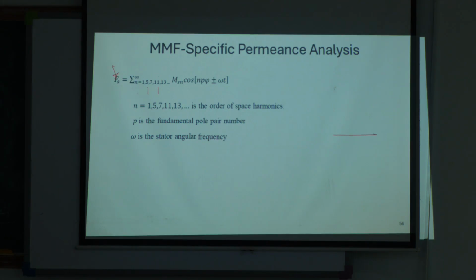If I take a 3-phase system, this is phase A, this is phase B, and this is phase C. If I consider this as positive sequence, if I multiply by 5, let's say this is a magnitude and an angle 0, this will be same magnitude but angle minus 120, this will be same magnitude, angle plus 120, right?